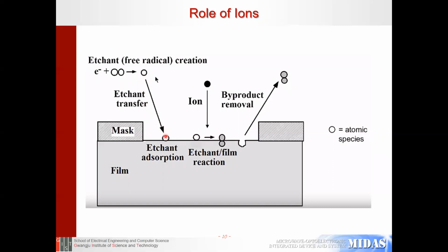If it is like chlorine, it just sits there. But if an ion comes in, that ion creates sites by breaking bonds, let's say silicon bonds, and when the bonds are broken, the absorbed agent can react with the material, let's say silicon, and form a volatile product, leading to a chain reaction of spontaneous reaction that forms a volatile product.